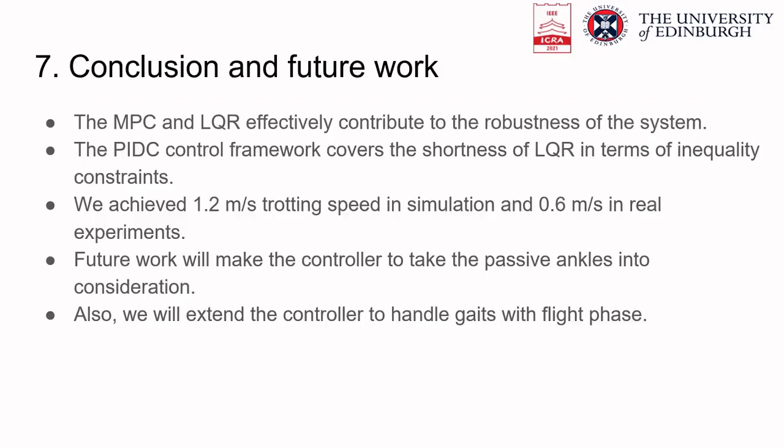Okay, here are the conclusions and the future work. The MPC and the LQR effectively contribute to the robustness of the system. The PIDC control framework covers the shortcoming of traditional LQR in terms of inequality constraints. We achieved 1.2 meters per second trotting speed in simulation and 0.6 meters per second in real experiments.